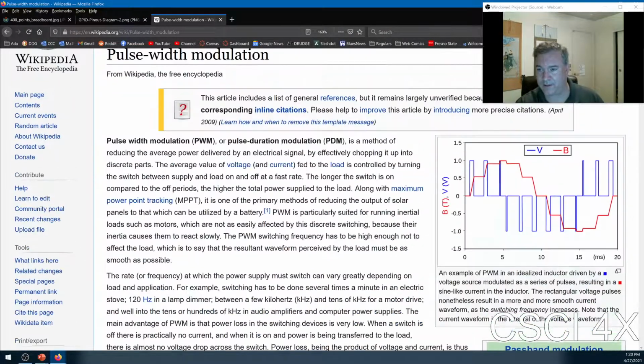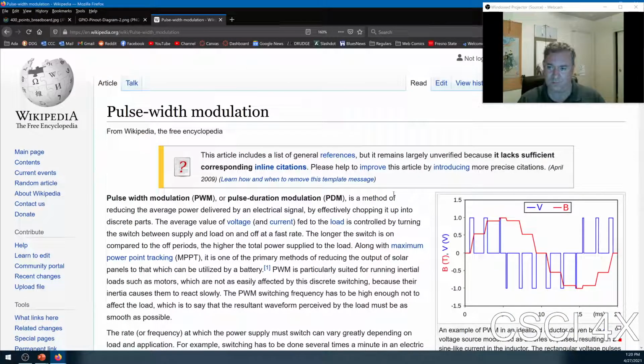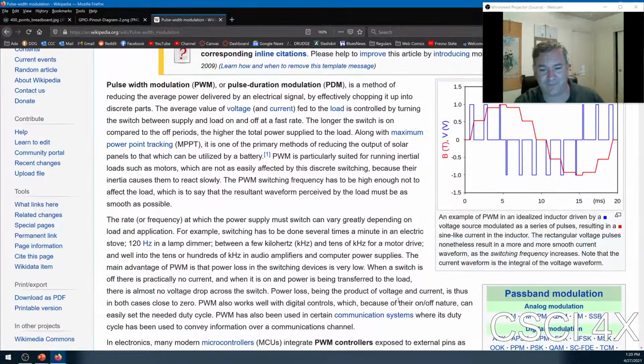And so by doing that, I would send to the PWM pin, turn on 100% of the time, down to 10%, up to 100%. And by playing with the sines and cosines and things like that, we were able to create this cool breathing effect of the LEDs. I think we actually wired them up separately, and so the LEDs would kind of go like this across the tank, making it look like it was underwater. It's a really neat effect.